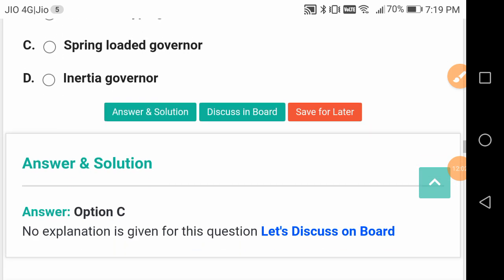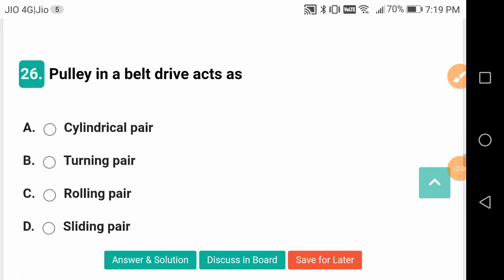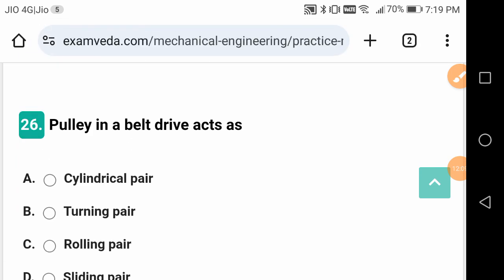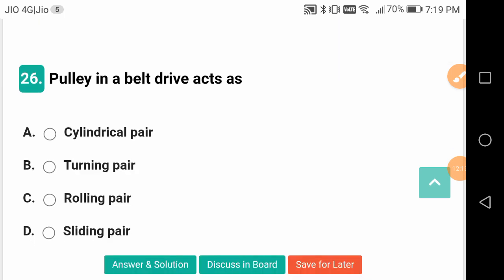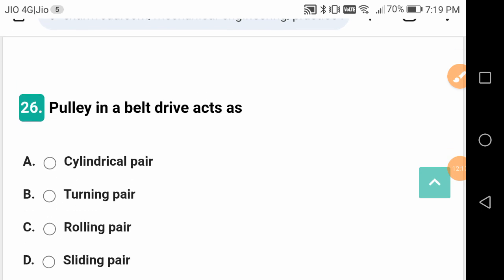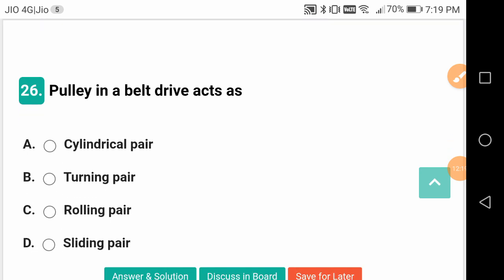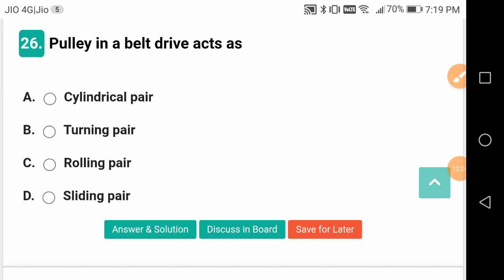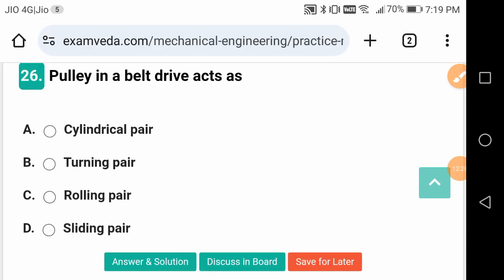Disturbing force should be equal to balancing force. Disturbing force is due to the rotation of the balls, and controlling force is the spring force in case of Hartnell or Hartung governor. In case of Porter and other governors, it is the weight of the balls, mass of the balls, and hence weight of the balls, and also other things mounted on the center part.